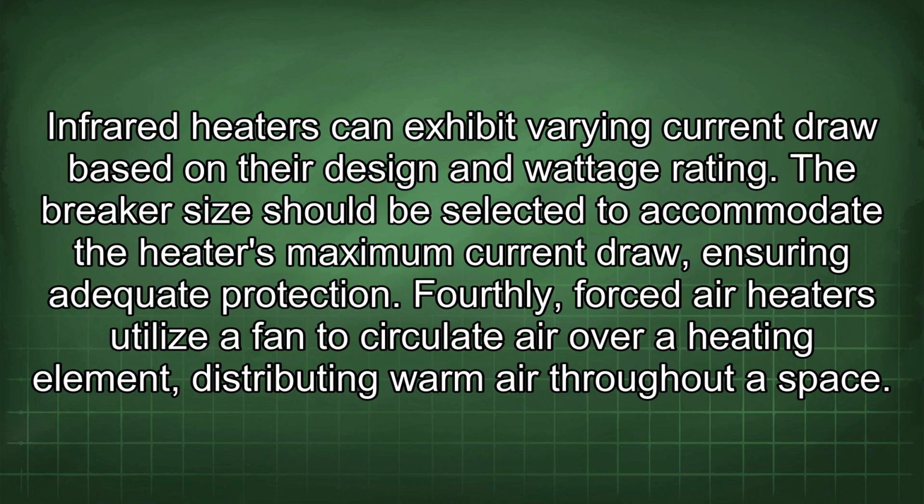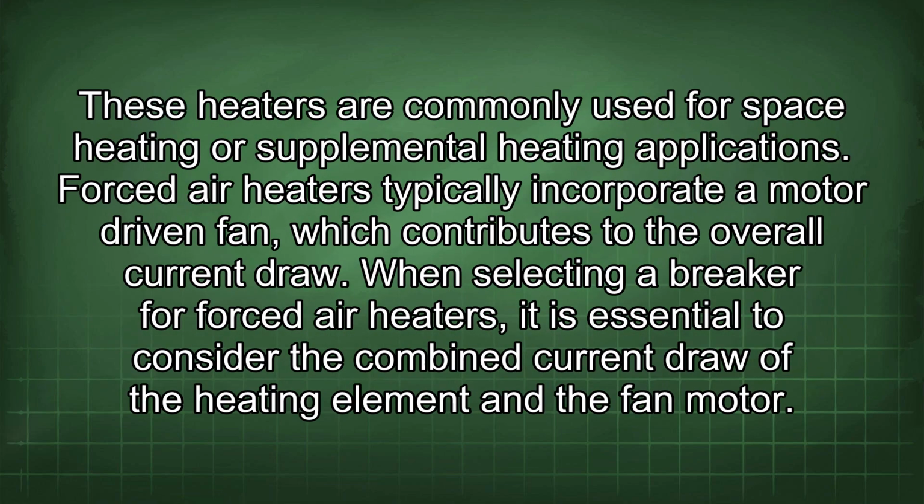Fourthly, forced air heaters utilize a fan to circulate air over a heating element, distributing warm air throughout a space. These heaters are commonly used for space heating or supplemental heating applications. Forced air heaters typically incorporate a motor-driven fan, which contributes to the overall current draw. When selecting a breaker for forced air heaters, it is essential to consider the combined current draw of the heating element and the fan motor.